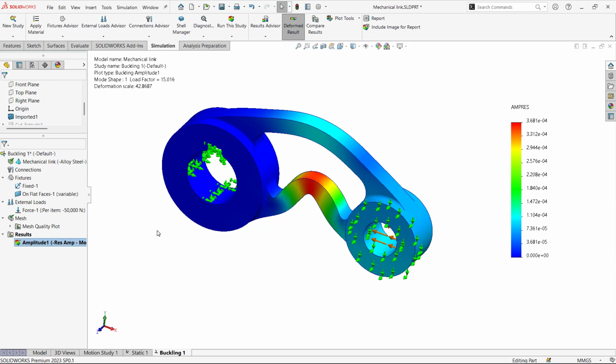Well, so in short, to summarize, we had gone through the basic structural analysis on the model, again to cross verify the structure and geometry and the displacement and the stress results. After that we had gone through the introduction to buckling analysis, and we saw the importance of the buckling analysis and why it is needed, and what linear and non-linear buckling are and how we need to consider them. In this particular example, we had considered one numerical problem, and we tried to implement it in the SolidWorks simulation, and we got the approximate same answer.